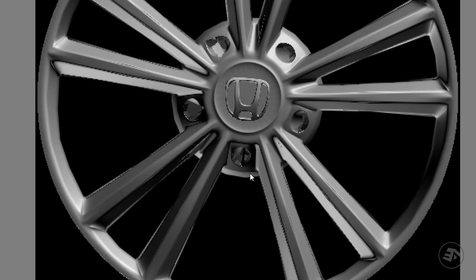Let's check the rendered texture. We clearly have a distorted texture. Why is this happening? The answer is because we do not have enough geometry to capture the high details, and some areas are not covered by the lower resolution mesh.